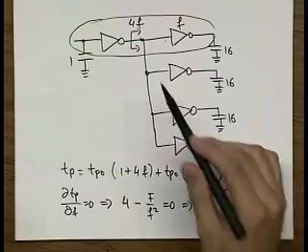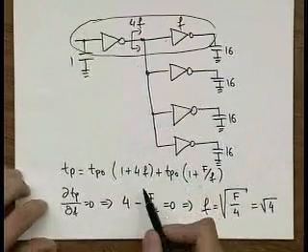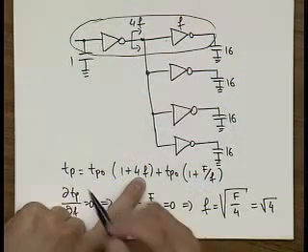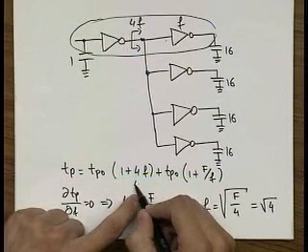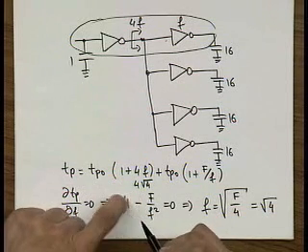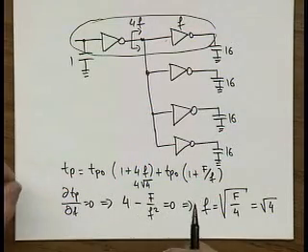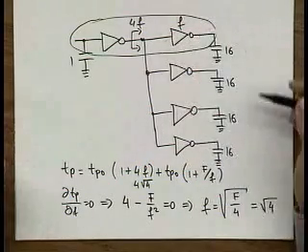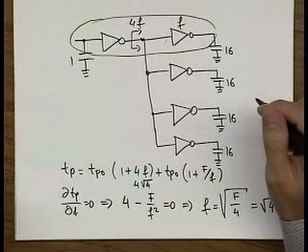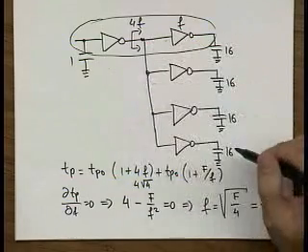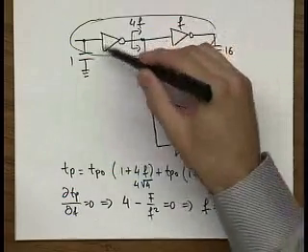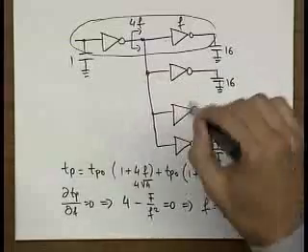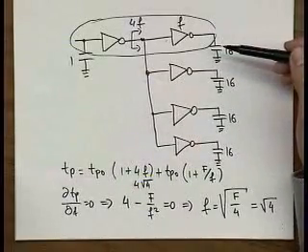But for just a quick analysis here, what goes on here is that you also have longer delay, because you had in the previous case just 1 plus f, so you had 1 plus 4. Now you have 1 plus 4 times square root of 4, which makes sense because of the smaller upsizing factor. Each of the stages has to carry more effort. It has longer delay, and therefore the resulting delay is longer because of this extra side load, which does make sense, right? Because you have to spend more effort in driving all these side loads with your gate, and that results in the higher propagation delay.